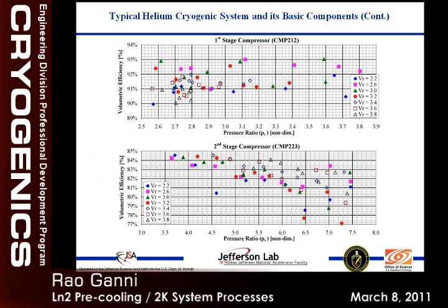Nowadays Howden is building screw compressors where we can tailor the built-in volume ratio ourselves. It's not like the olden days, where CHL1 has a fixed volume ratio that we can't change unless we replace the compressor. Now the replacement compressors have an adjustment where this final volume is in our control. So we can adjust the built-in volume ratio to fit our process more efficiently. That's what we installed at SNS.